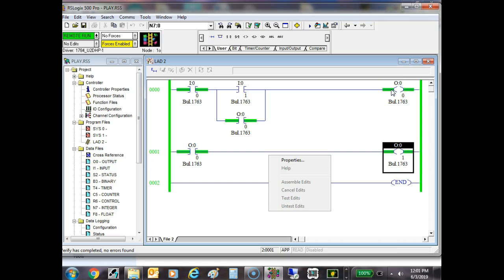If you're out in the industry and you've got a stop button and a start button, this is the circuit right here. You hit the start button, you let it go. And it's a momentary contact button, so it's only made when you press it. But it seals itself in, right? You understand? So this is a seal-in circuit. Some people call it a memory circuit. Some people call it a 3-wire circuit because there are 3 wire numbers between here and there.